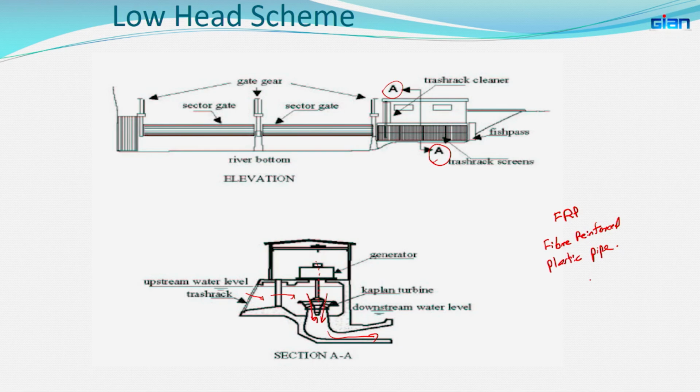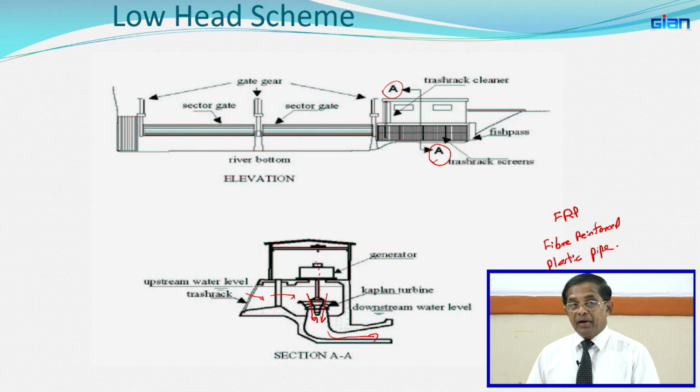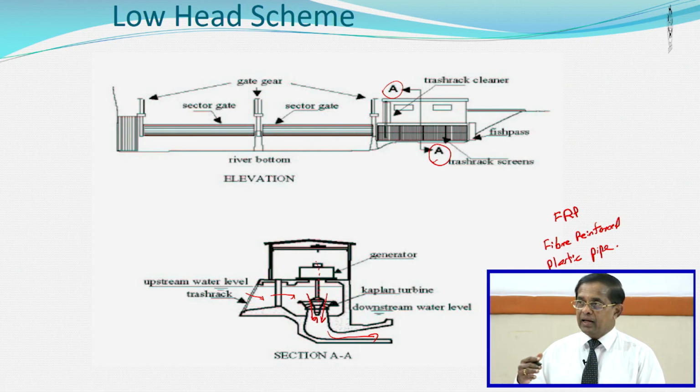So, in Sri Lanka I have seen several power plants which use FRP pipes as penstock material for low head projects under similar conditions, right. Your head may be 20-30 meters, even less. So, in that case this configuration is good, and also these materials. So, these are in addition to developing high head projects, that earlier we looked at, where you have hilly area and the contour lines to get the various heights, and then develop a project with a diversion weir and canal.